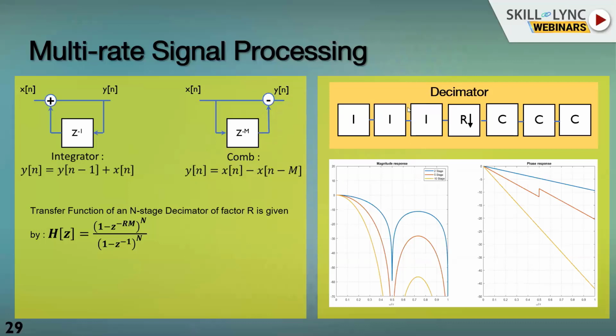So I have shown here the decimator, which is decimating or downsampling the signal by a rate R. The rate R here is 4. So you can see when we do decimation, the spectrum of the signal expands by the same factor R. And we have to do an anti-aliasing filter before doing the decimation. So we have to filter out the signal so that it has only this much of frequency, and then when we are decimating, this will expand and become from minus pi to pi.